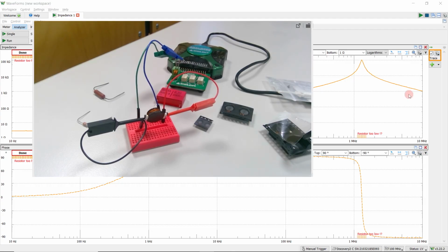It's the parasitic capacitance between the windings. We have many, many windings and they are very, very close together. So it's like lots of small plate capacitors that are close to each other and that form some kind of capacitance inside this inductor. And this is what can be measured above a couple of megahertz, or at least at 10 megahertz, this behavior is very pronounced.